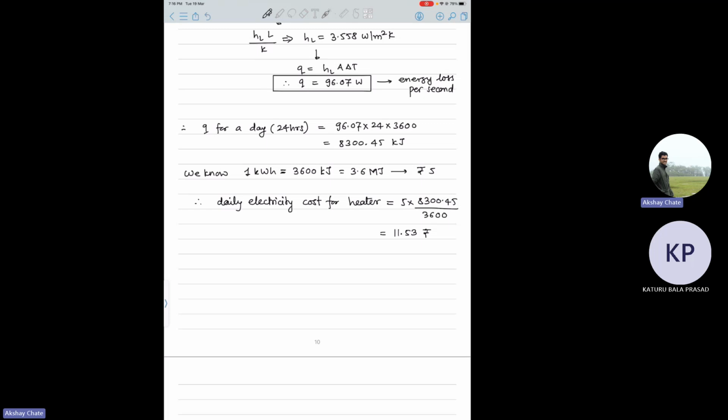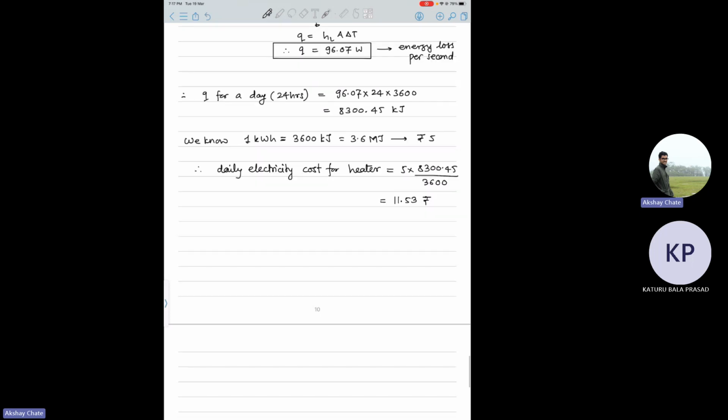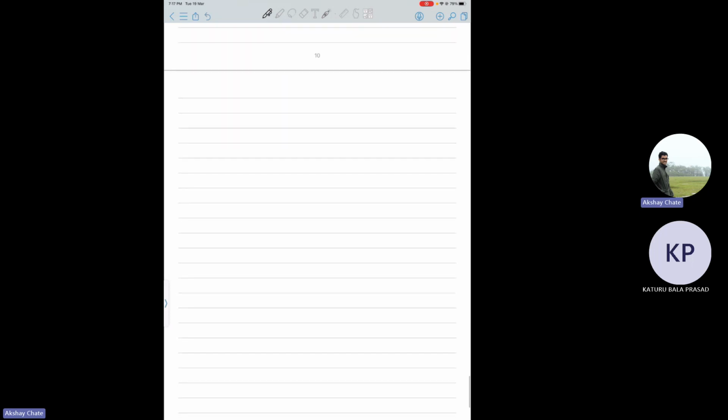Then you'll arrive at a Leidenfrost point. Then again, after that, if you keep on increasing your delta T, or the temperature difference between saturation temperature and your current fluid temperature, you'll end up in a film boiling region, where the whole of your heating coil will be covered by the vapor. And what about the variation of h with respect to delta T in all those regimes? This was covered in the class also, but for the sake of revision, at least you should remember it like this.